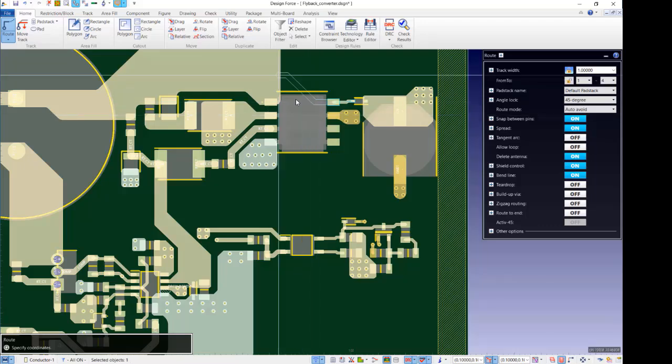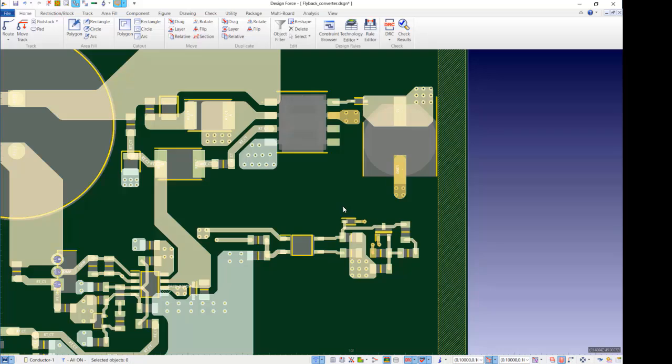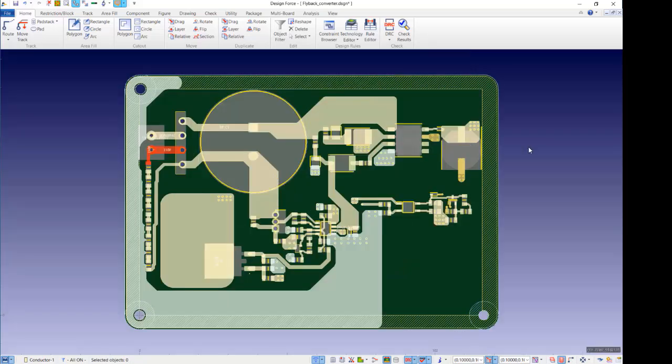Like if I was to come in here, obviously there's a larger space between these rather than the optocoupler here. You can just see it wants to start stopping me from routing up here. I can't push this across here any further, automatically stay into those rules. Okay, so that's that one. So the next one then is we're going to just run a DRC, have a look at where the errors are, and then see if we can fix them or not. If we can't, like in one place on here, I know that I have to add a slot, and we'll do that. So the next part I will run the DRC.